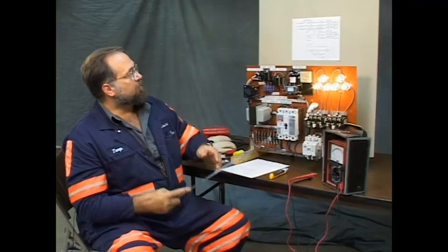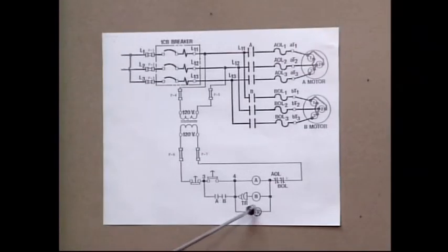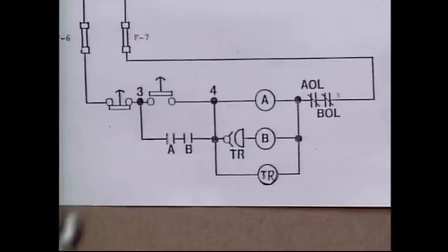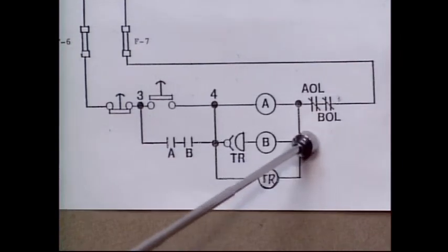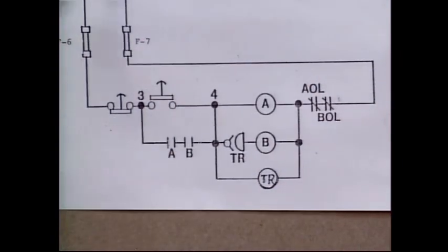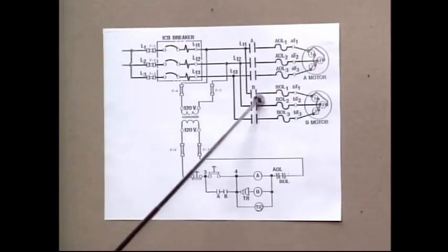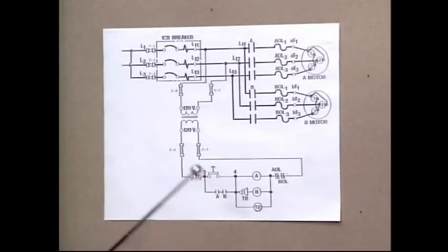Now, the timer, its coil is being driven now. The mercury is being pulled through the relay. When the mercury makes the contacts, B coil is energized and it pulls in. It has a circuit. It's the same return as A through the overloads. B closes right here. These contacts close. The B coil is a magnet.